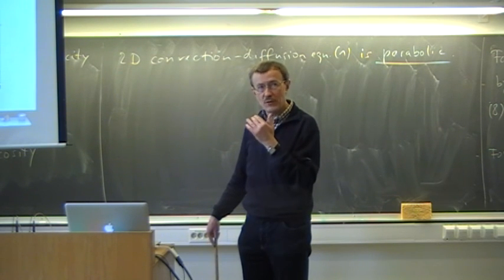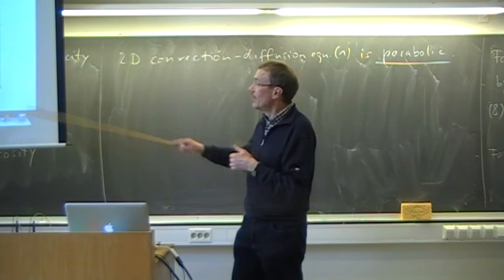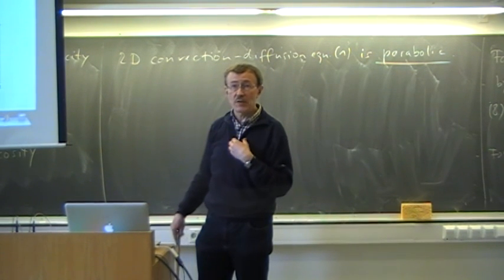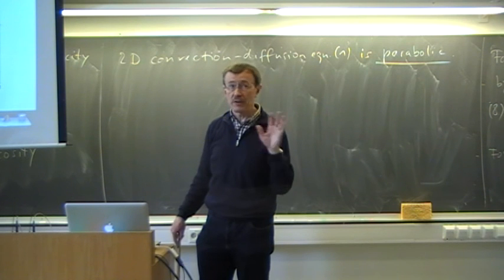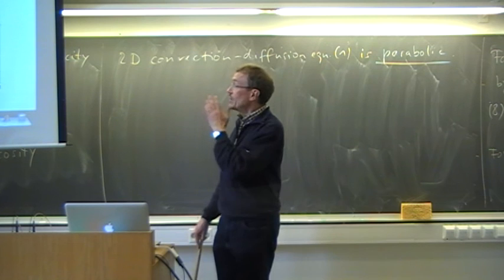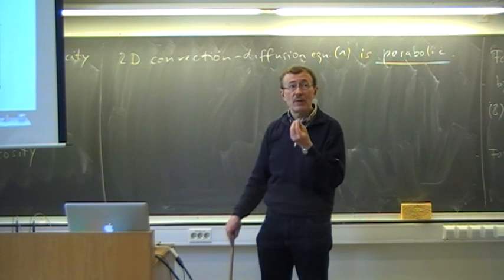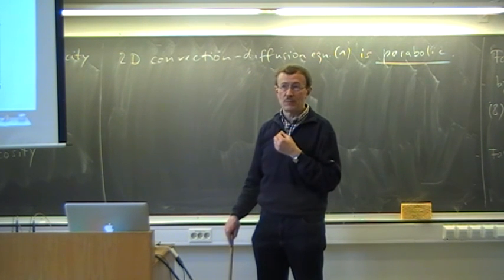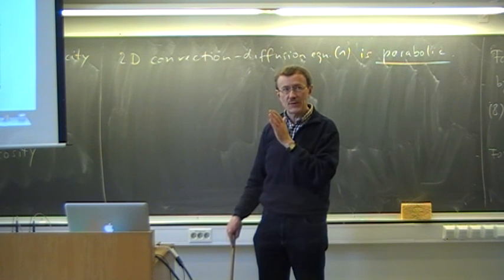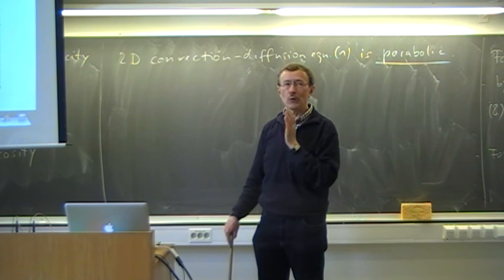We want to have the physical diffusion, and depending on that, the amplitude will diminish. What we have seen before, when we discussed the linear advection equation, that was numerical diffusion. It was nothing physical, just a numerical effect. But here we want to estimate the physical diffusion. So we must be sure that what we are computing is physical diffusion and not numerical diffusion.